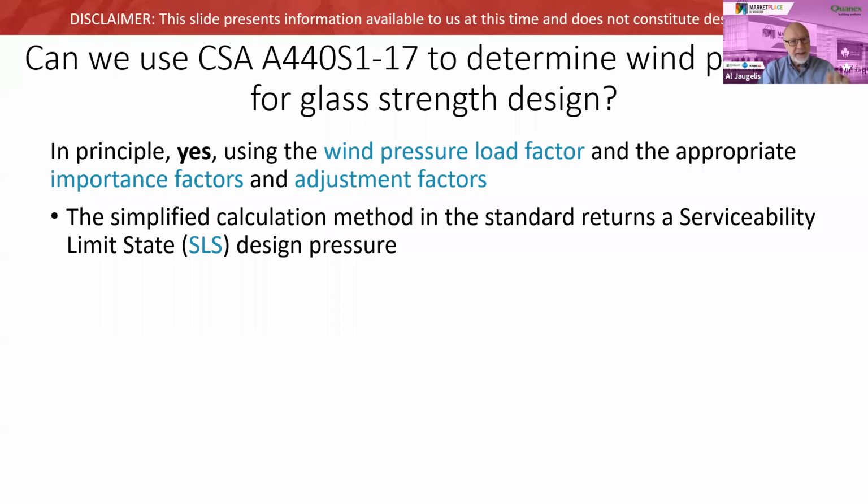And we're just analyzing it for deflection, not for failure. Right. It gets a little bit more complicated than that, because in NAFS there is no deflection limit for class R and LC products, but a deflection limit is always required in non-Part 9 buildings that are being reviewed by an engineer, because they know full well that the assumption in the glass strength standard is that the edges are supported rigidly enough not to deflect more than L over 175 at the specified design pressure.